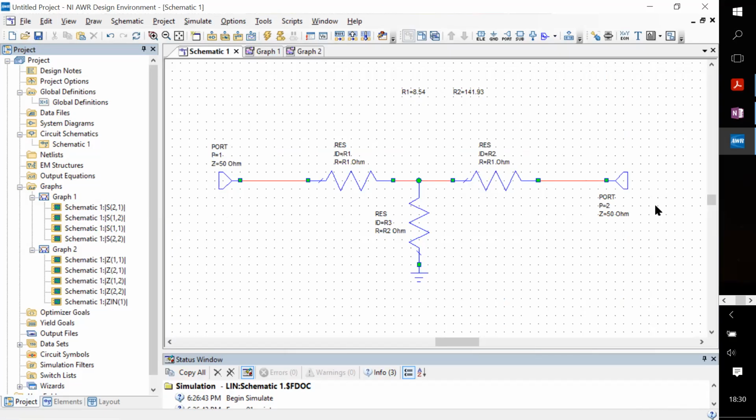There are typically three types you can do. You can have the ports open. You can have the ports short circuited, which actually means connecting this point to ground like this, so that you have a current, maximum current flowing through it, not through 50 ohms, or you can have it connected to a 50 ohm circuit. That's called a load termination. Okay, so the convention must be that if you're measuring the quantity Z in, then all the other ports must be terminated with the port impedance, which in this case is 50 ohms, and that's why you're getting 50 ohms.